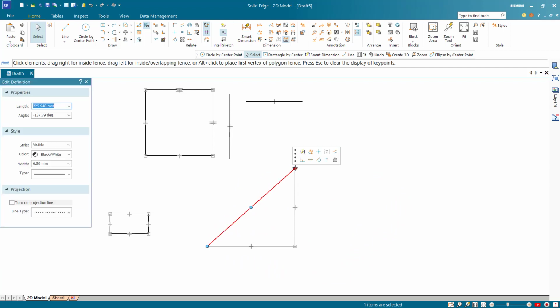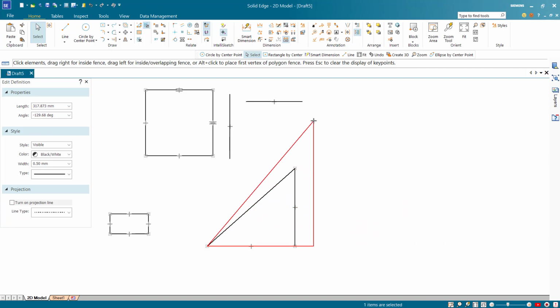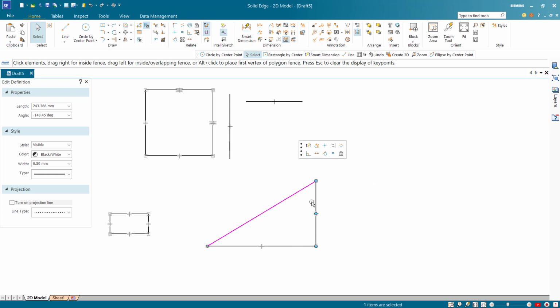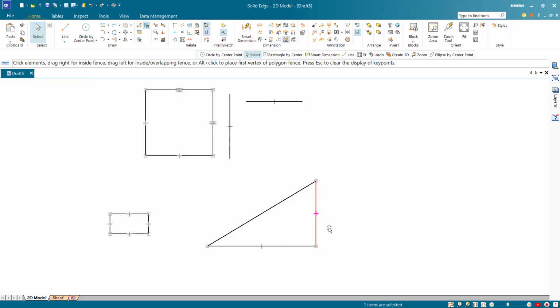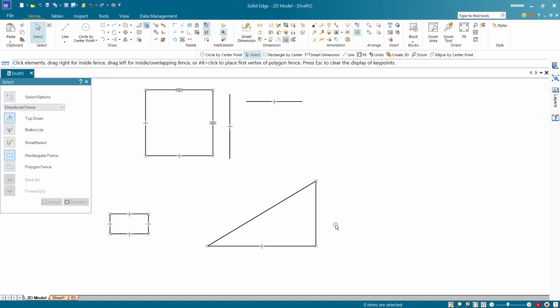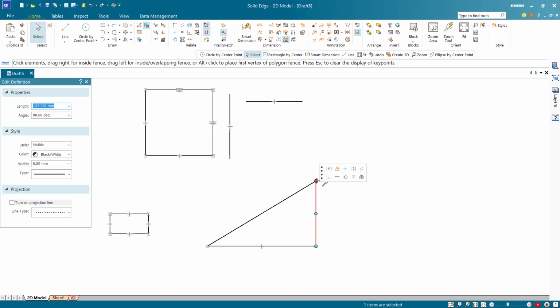And if I touch on this line and grab the corner, you can see it'll move around. That line will, because there's no constraint on that line. But these other two lines are horizontal and vertical. Now, I could delete this constraint. If I just box pick that and hit delete from the keyboard, the constraint is gone. Now, if I come back to this line and grab that corner, you can see I move that around accordingly.